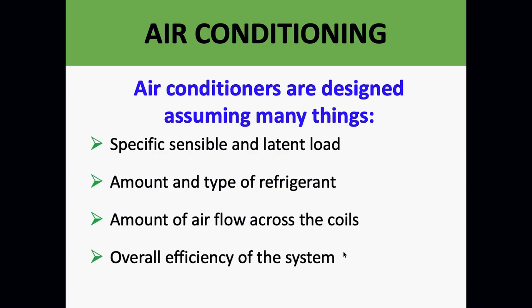Did you know it's against the law to install under 12 SEER? 12 SEER is a measurement of the seasonal energy efficiency rating. It's SEER, S-E-E-R. It looks at an average of how much energy that system will use over the course of a year. I can't install under 12 SEER anymore. In some states, I can't install under 13 SEER because of the requirements of efficiencies.